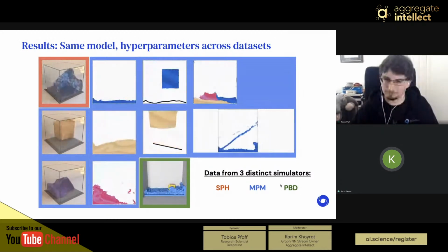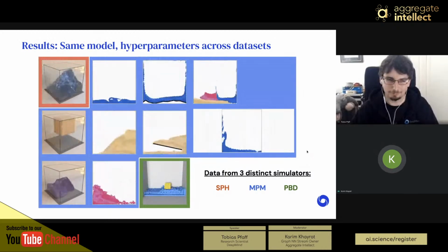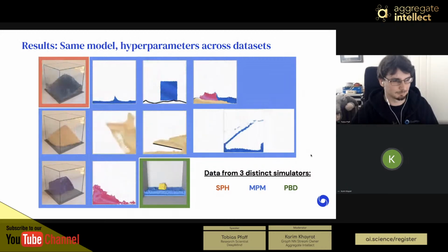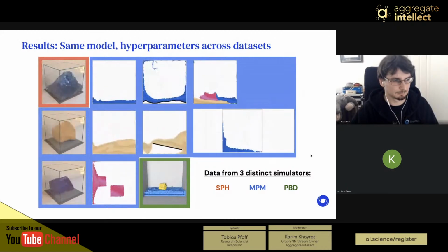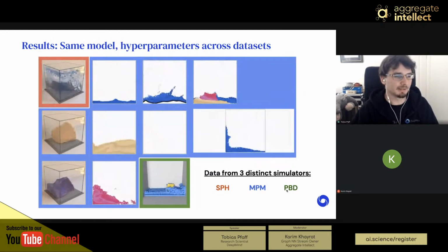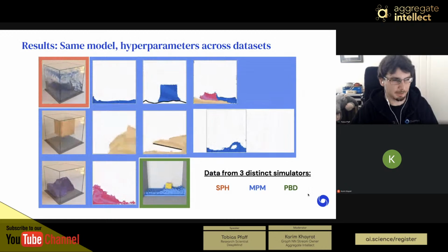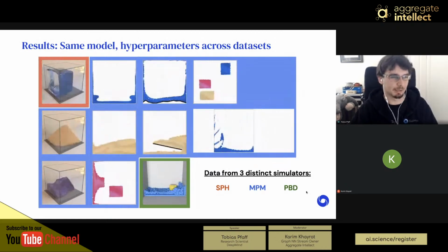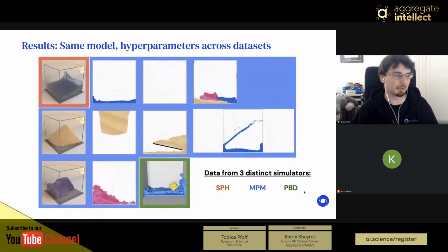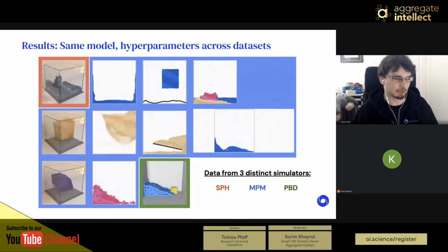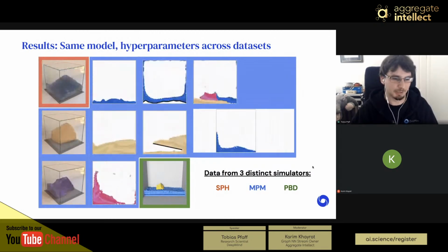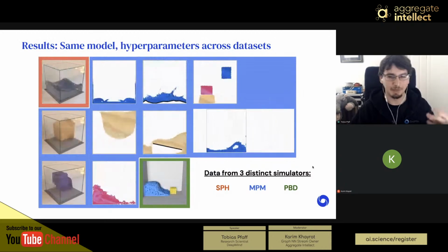So essentially, on the big picture, what's the main difference between these mesh-free methods and the graph neural network method that you've been using? Well, these are all mesh-free ground truth simulators. I can go into that a little bit later: what actually happens if you have a ground truth mesh? We don't use any ground truth mesh. We have a GraphNet learnable simulator that just gets connectivity by proximity.